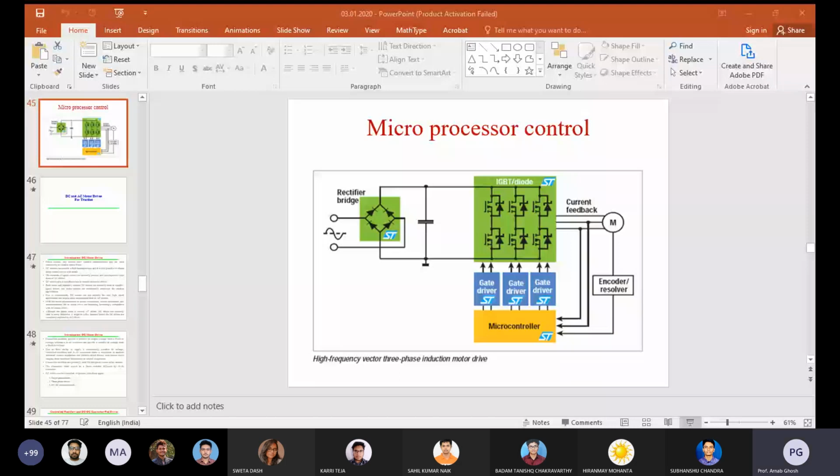Here you can also see that VF is your field voltage. Again you are giving an AC supply through the direct bridge rectifier or the control rectifier, which directly comes to the field current IF. The armature and the field are also coils in nature, so if you give some pulsating DC, automatically you will get a more or less constant value of DC. So those advantages are there. This is the control rectifier fed DC drive.